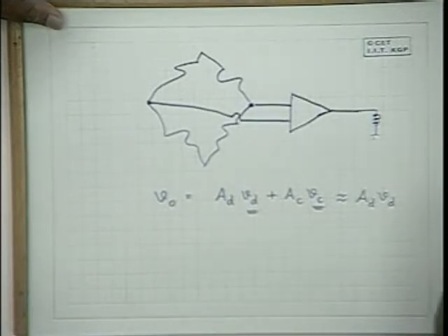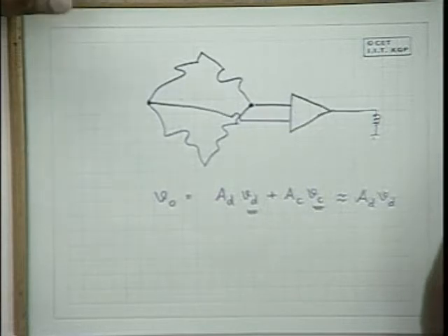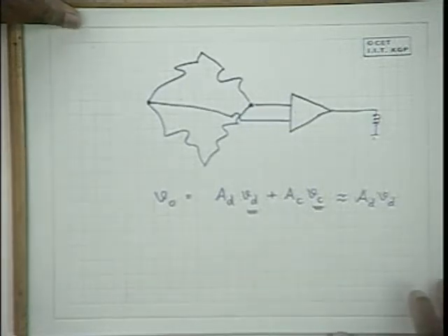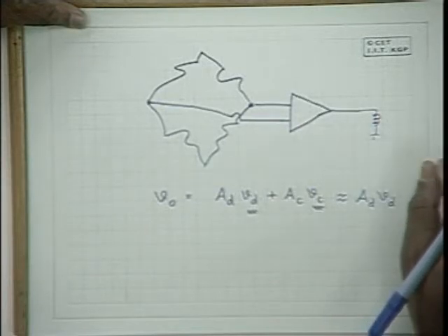So if we get a common mode signal which is amplified, is it possible by any other means to filter it out? So the question there is, how do we reject the common mode signal? In the differential amplifier circuit itself, we design the circuit such that for the common mode signal, the gain is negligibly small.